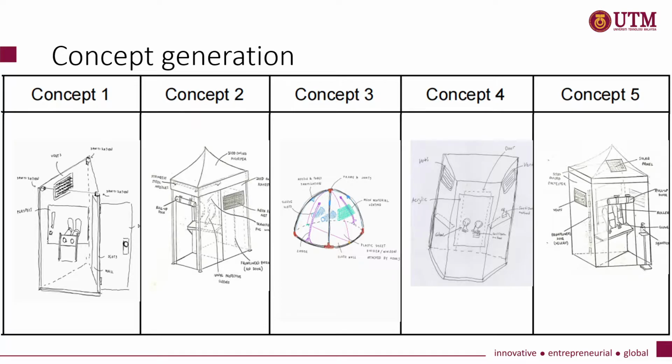The first design has a triangular shape as a whole, acrylic perspex as the wall material, a door entrance type, roller sleeves mechanism, normal air vents, dovetail slots for installation method, and clear acrylic for window material. The second design has a rectangular shape as a whole, Oxford polyester as the wall material, roll-up door and zip as entrance type, vinyl protective sleeves, mesh flynet ventilation, and stainless steel nozzles and tubes for sanitization method.